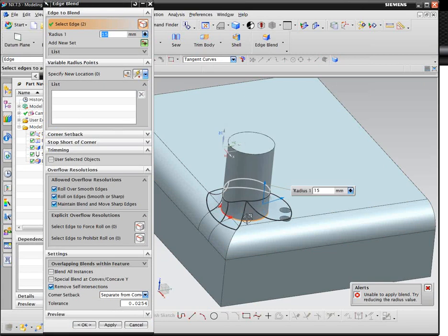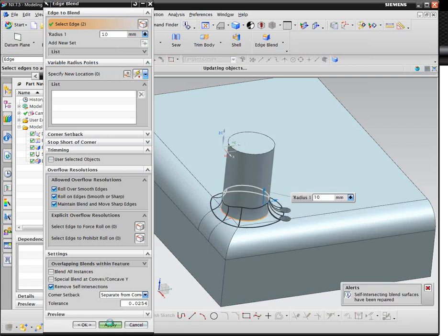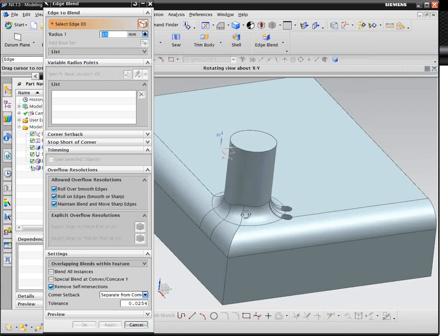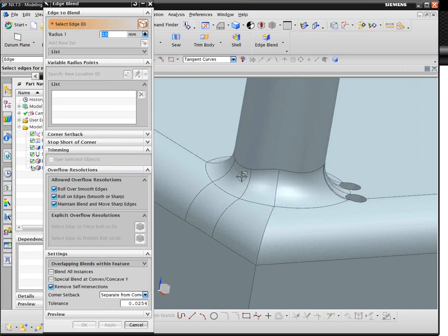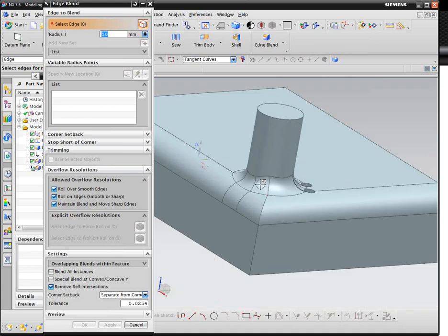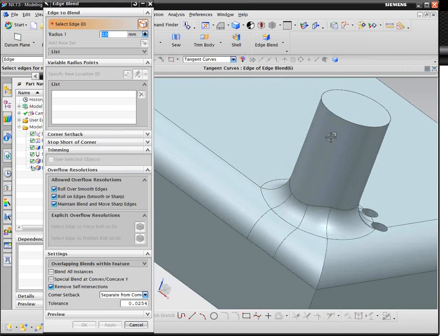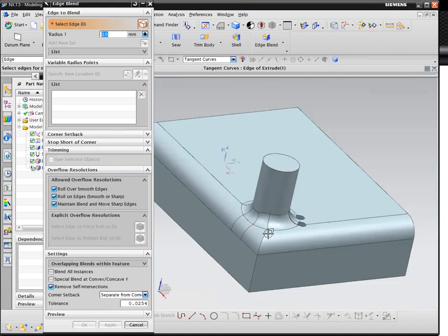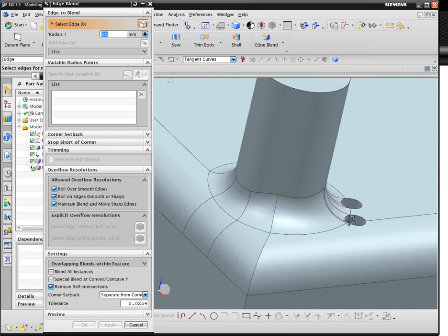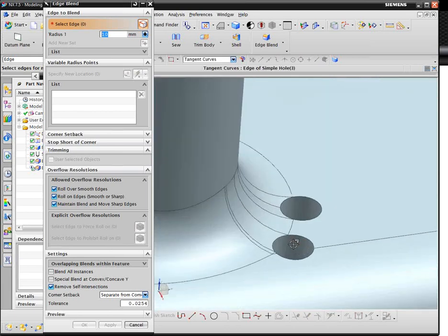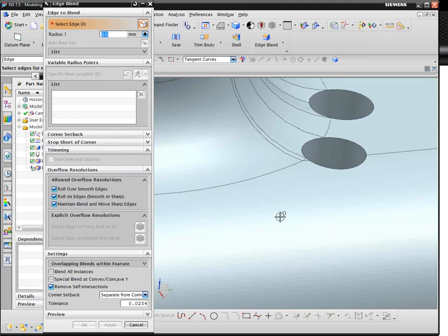Got an interesting configuration there. My blend radius is a little bit large too. So essentially, it joined these two blends together. I had to do it separately just because why would you blend the boss at the same time you blend the edge? I don't know. You can if they're not too close together, but as a separate feature, they blend together and play together quite nicely. Your boss blend rolls right into the edges of this block's, the base plates blends, and it doesn't mess up your holes either. It kind of rolls into that nicely.